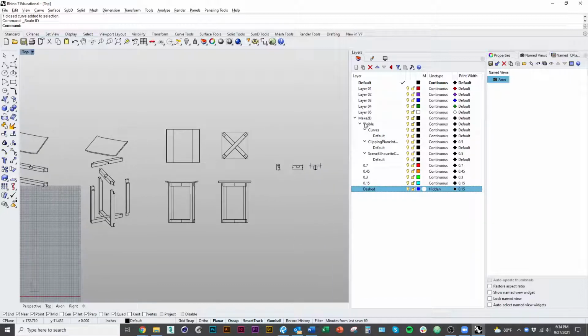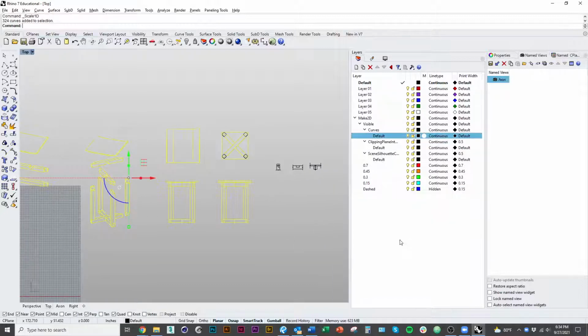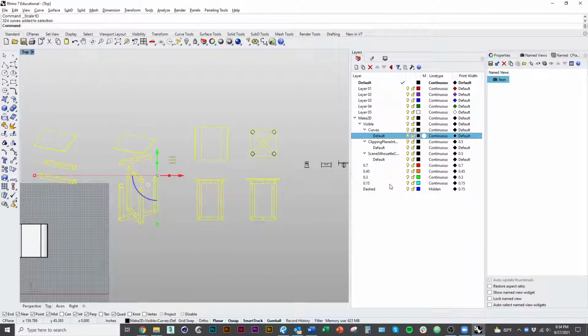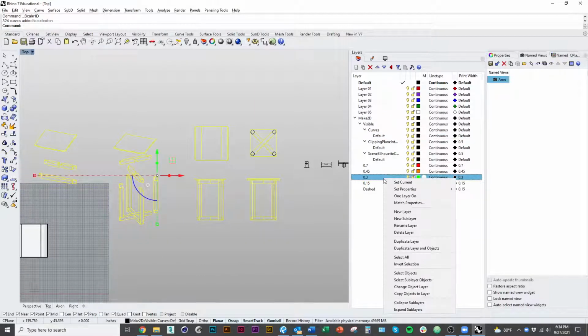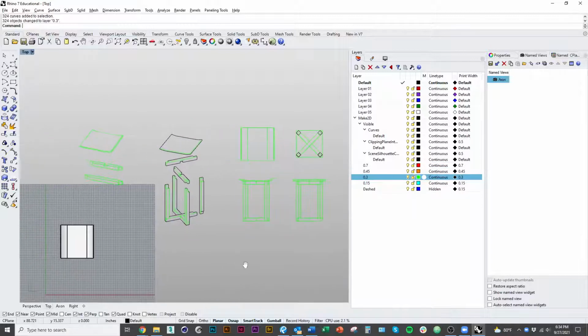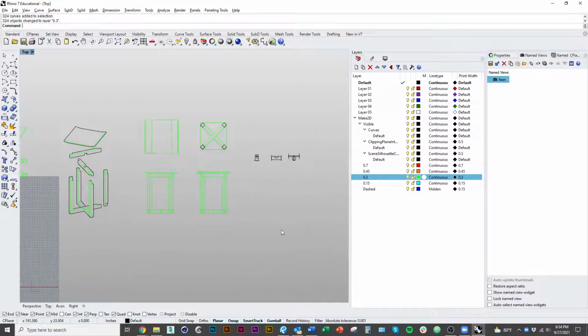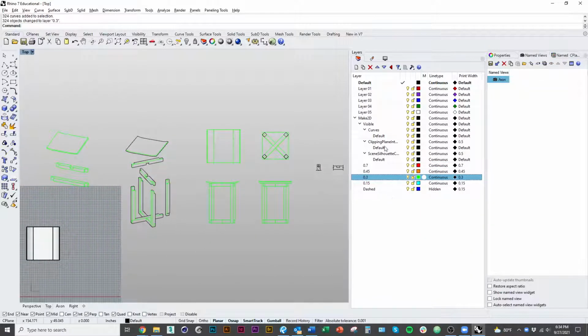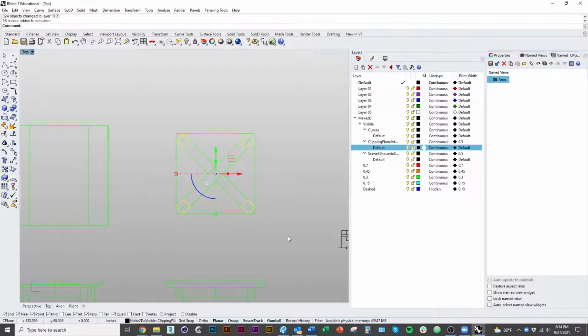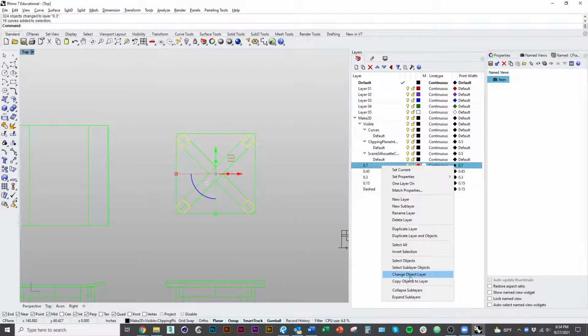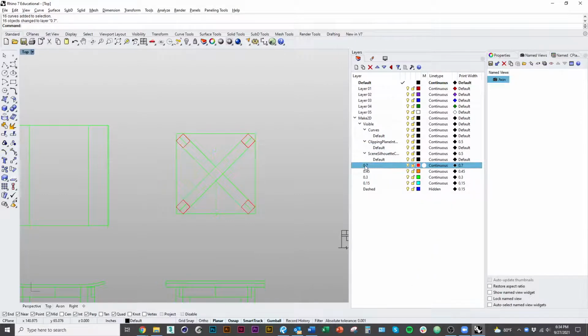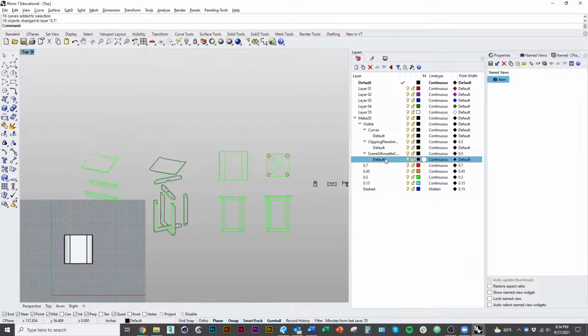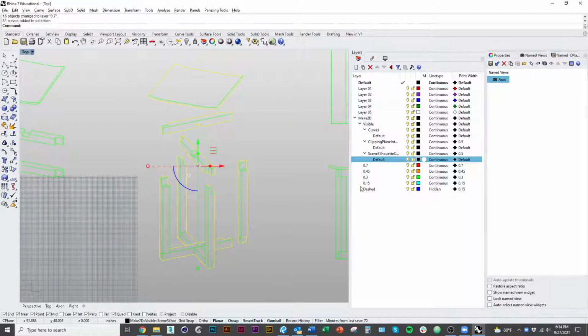And I like to start by going under our visible. So most of our lines are there. If I go to select objects, I'm just going to put that on the lightest, maybe the second lightest line. Most of our lines are going to end up on that layer anyway. And then I would do the same for my clipping plane intersections. Now remember, any kind of cut on a plane or section is our heaviest line weight. So I would go ahead and change that to my heaviest line weight. And then my scene silhouette, I could do the same, or I could maybe put it on